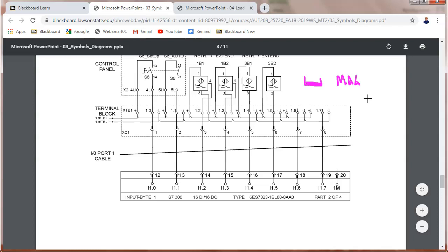If it's a 3-wire sensor, it's either a Hall effect or a magnetoresistant, which basically means nothing to us. It requires 3 wires. If it's a 2-wire sensor, then it's a reed switch, because reed switches don't have to be powered. But they're both magnetic sensors. Like I said, I'll run this off and give it to y'all next class, if I remember.